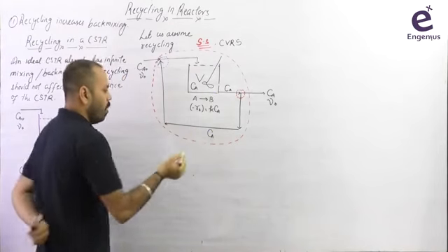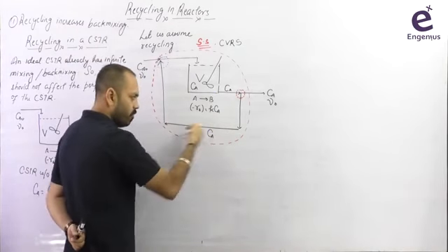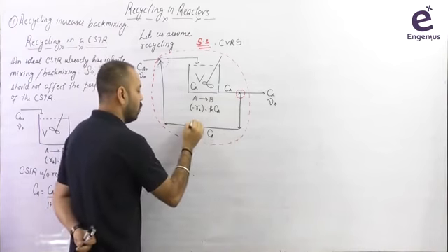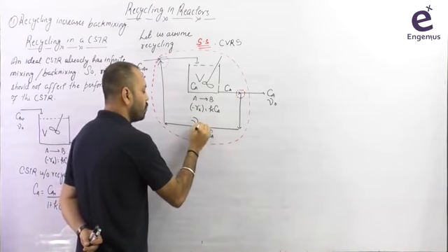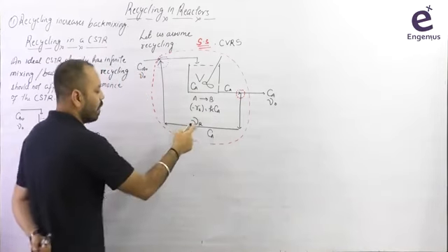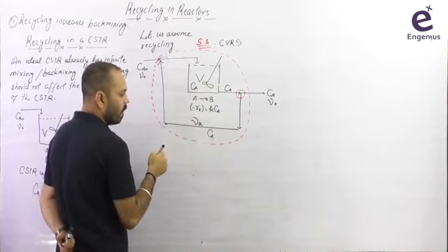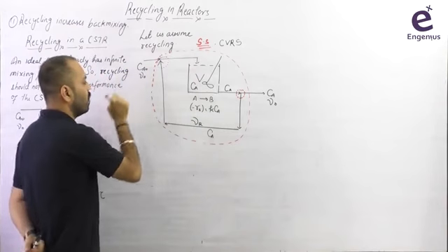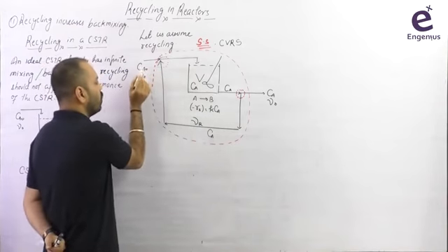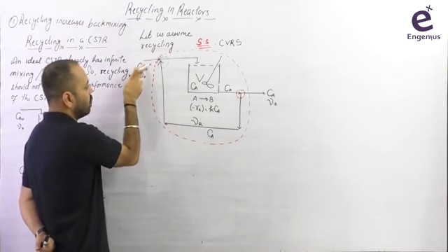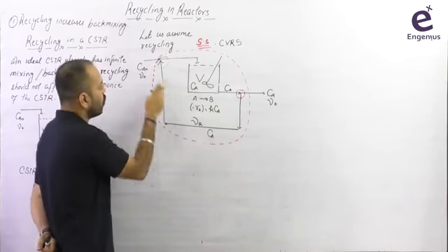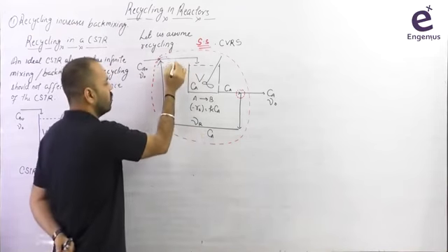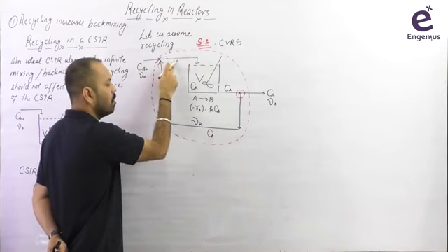Okay. Now let us suppose the flow rate of this stream, you can give some name to this flow rate, right? Let us say that this is the flow rate of the recycle stream, the volumetric flow rate of the recycle stream basically. This recycle stream goes like this and then it combines with this reactor feed. Now when two streams of different concentration are mixed, this is Ca0, this is Ca, they are going to form a new concentration. So here the concentration cannot be Ca0, it cannot be Ca.